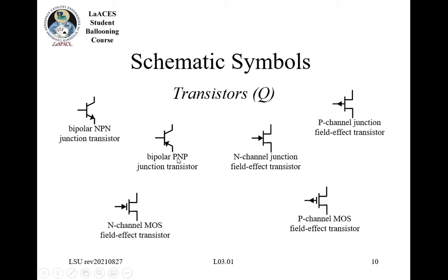The PNPs, oftentimes you'll see them flipped up from this. So this is a little bit different configuration, but there are reasons to use one or the other. Again, the most common one is the NPN, but sometimes you may have a reason to use the PNP. If you start getting into more complex designs, you might want to spend some time looking that up.